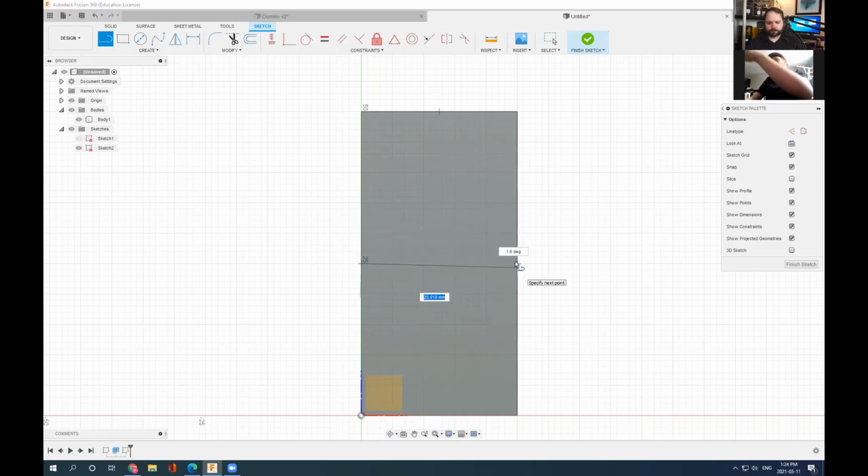And it's going to tell you that we've made 0 degrees of rotation. If you have anything in there, you don't want it to be there. And you're going to see that triangle again, and it'll lock on. It should be locking on for you. And you can click right there, and now you've drawn a line. Importantly, this line is a solid line, so it is part of the object. But for this purpose, that line is only going to act as a reference for us.